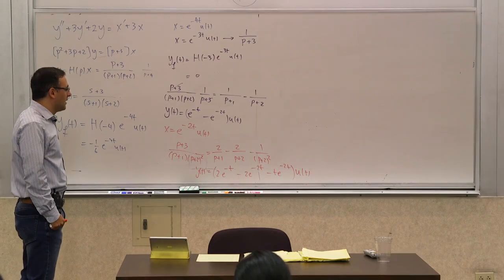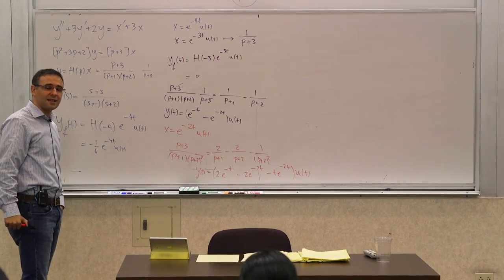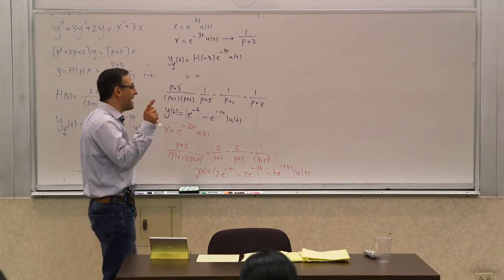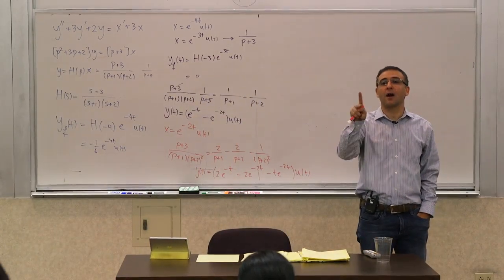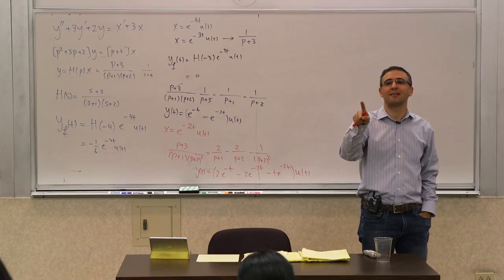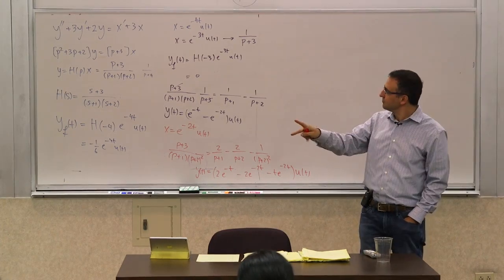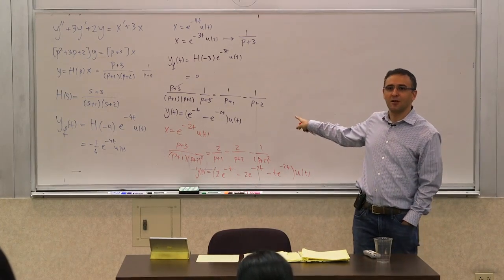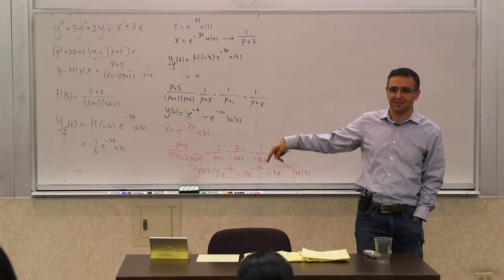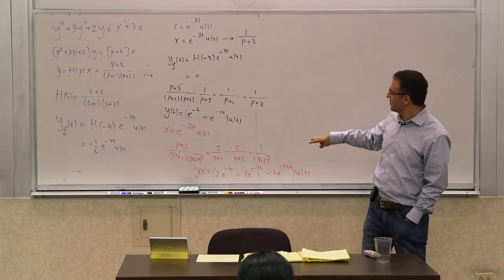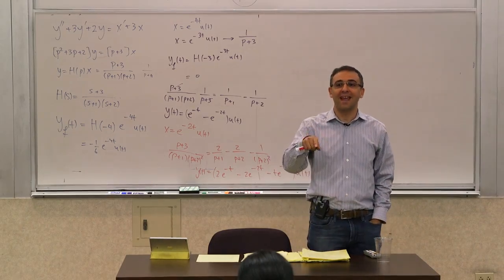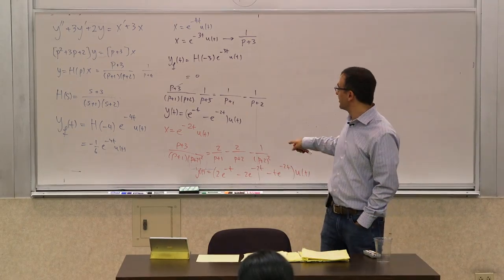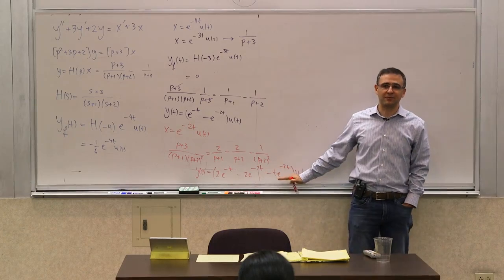Correct. Now, you earlier mentioned resonance. And resonance is related to these natural frequencies, but in a different way. That happens for a pair of complex conjugate poles, for example, in an LC circuit. Not two poles of the RC type. So we'll see examples of that. It's not unrelated, but this is more general, because we are dealing with complex frequencies.